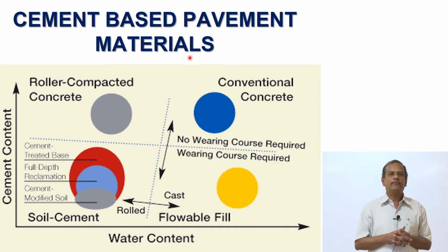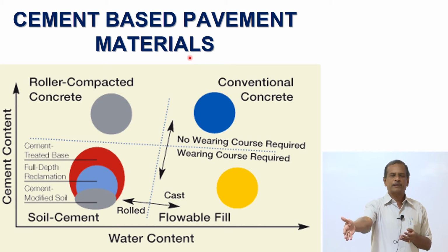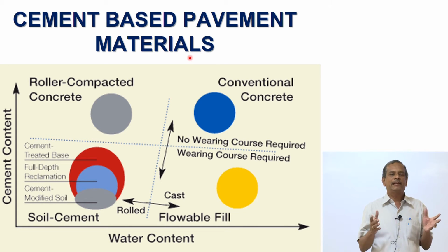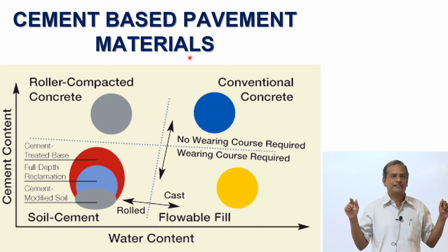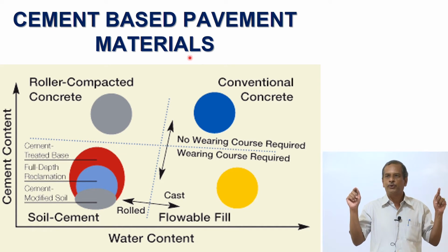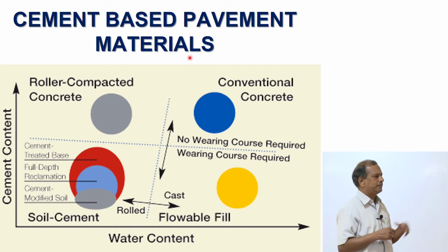Earlier, what we were talking about is that this is the strength of the subgrade, so what should be the thickness of the pavement. Now, I can ask what strength you need: 5, 10, 15, 20, I can give. I can try to modify the soil. Now, these soils are called engineered soils. You can get whatever strength that you need. So, I can use a soil cement.